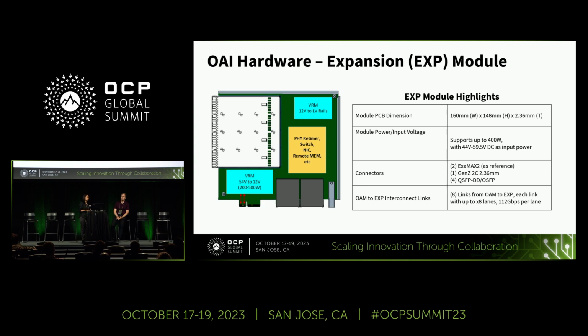Basically, one of the vendors has an 8-lane solution at 100 gig. So in that case, with 4 OSFP modules, you'd be using 4 retimers on this expansion module. And in the case of Broadcom's product, we have more integration. We have a 16-lane device. But the reason the 400 watts is specified is because the expansion module spec is envisioned to have more use cases beyond scale out. So that's why the power is defined as that. And then the links that we are talking about are at 100 gig, which is the speed.